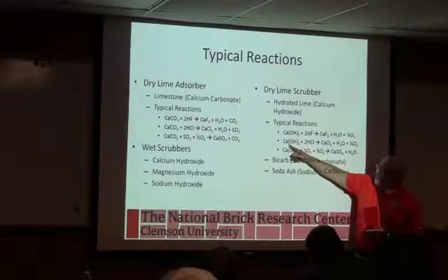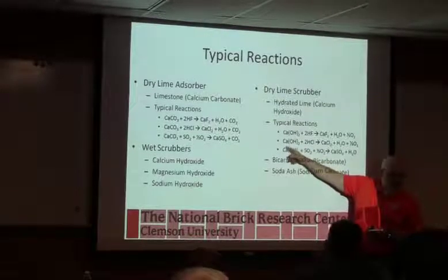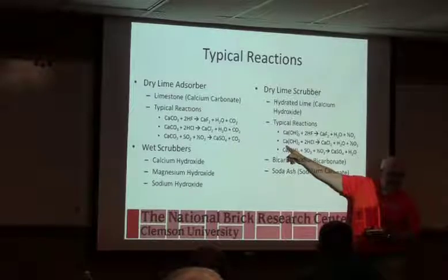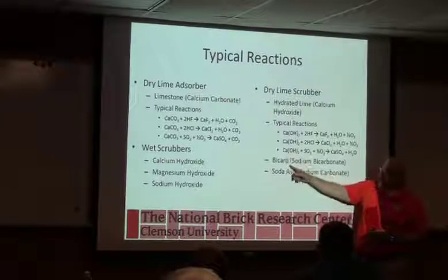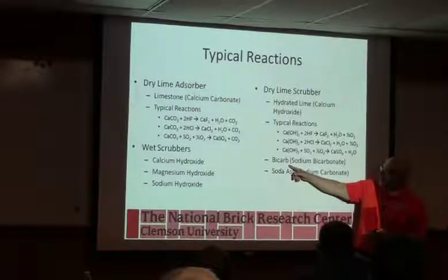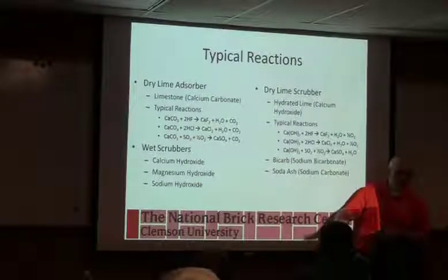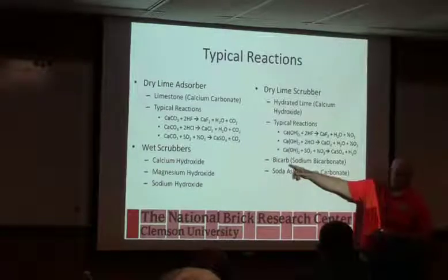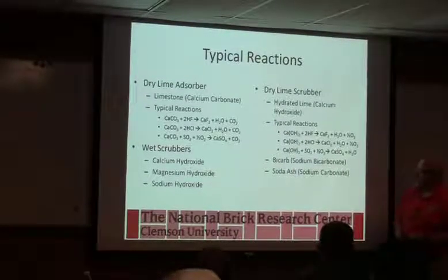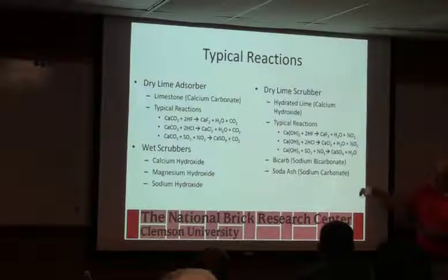So they try to control with the lime as their primary control, but when fire clay starts getting in the hot zone and the sulfur starts to go up, it triggers a feeder for the bicarb to bring the sulfur back under control. Once it falls below the level where they want it, the bicarb shuts off, and then the calcium hydroxide kicks back in.